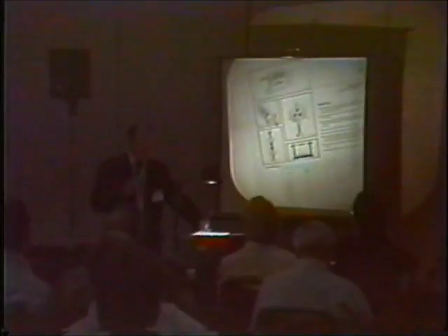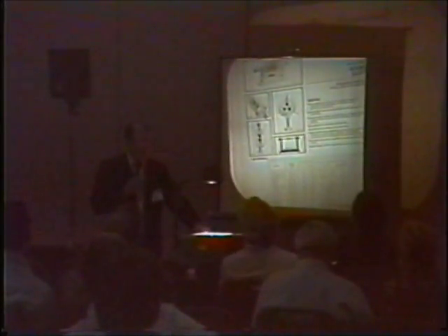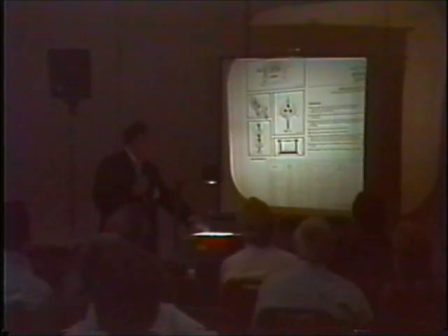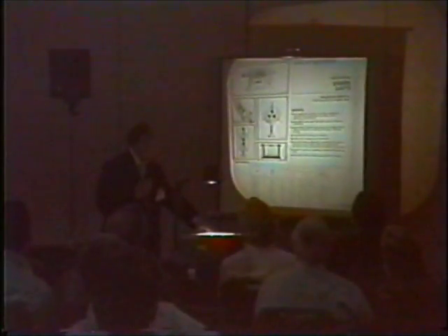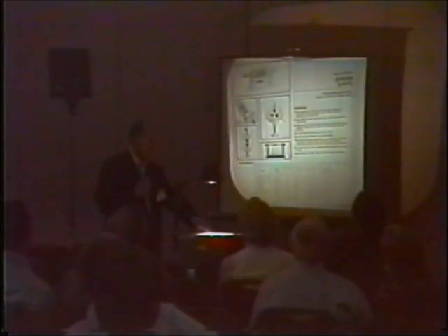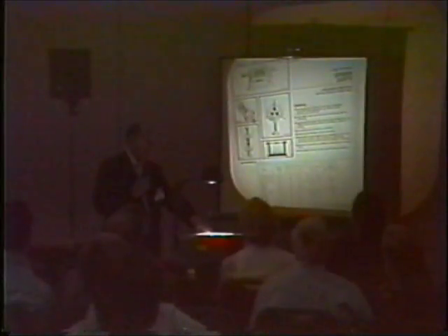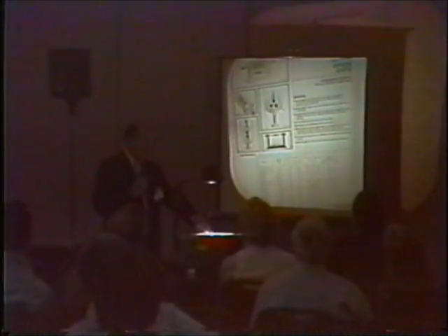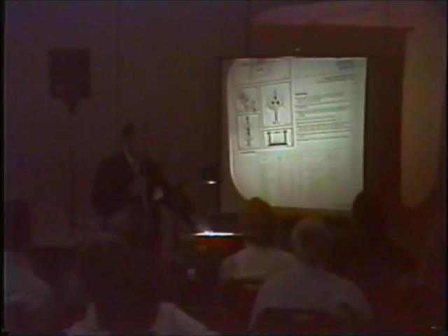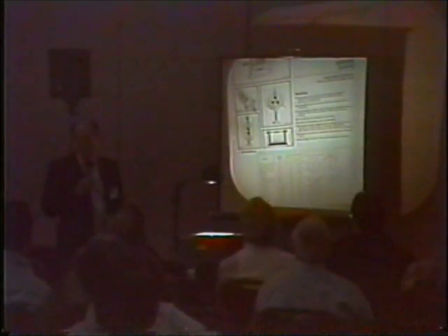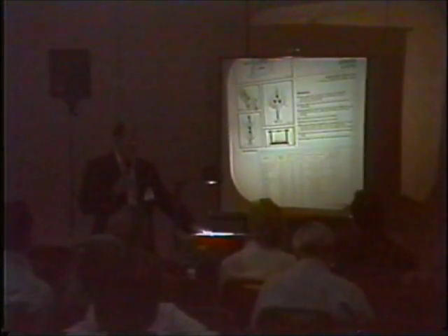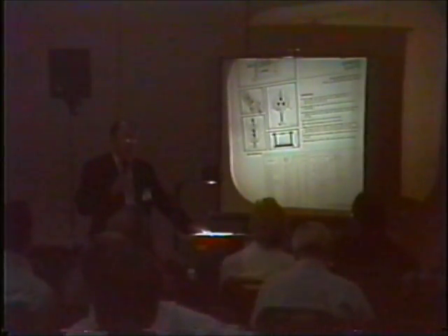Okay, I'm going to show you a different kind of spark gap. I'm trying to get it to where you can see the whole thing, where you can see the dimensions. Those balls that you see in there are carbon balls, and the reason for that is that they don't evaporate like your metal ones do.